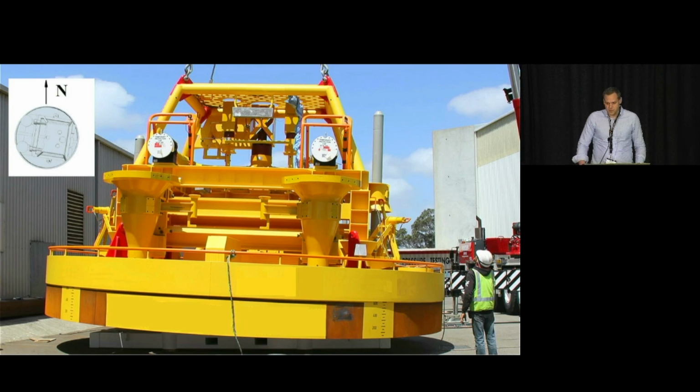From a scour perspective, what's important is the fact that it's a geometrically complex structure. It's porous, you can see through it. It's a circular mud mat, and on top of that is a structure that's roughly cuboidal in shape. You can see around the bottom here we've got a skirt. The skirt's about 600 millimetres deep, and the diameter of the mud mat is about 8 metres. It's orientated as shown in the top left here, so you can see these 2 circular parts of the structure here. They're sort of facing west, approximately west, as it's deployed on the seabed.